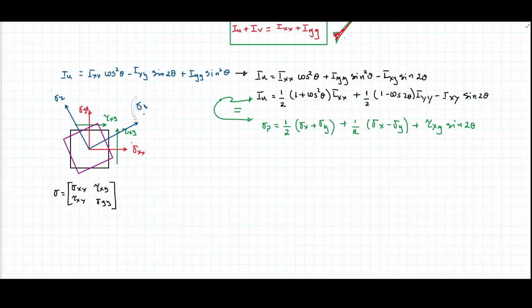We move this one also to here, and then we select this one, and let's remove this. Then our mission in that chapter, now I'm simplifying the case because this is a 2D representation, was to find this angle, to find the principal stresses, and then taking those principal stresses to the failure theory of our choice, or of our selection or convenience, and then do that.